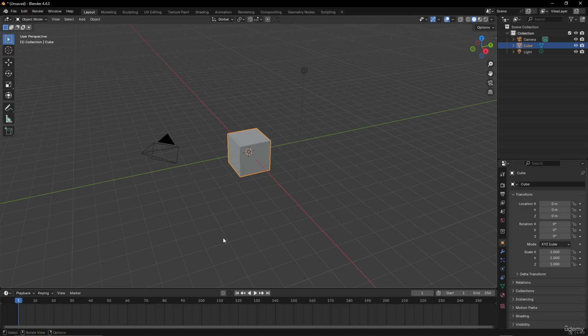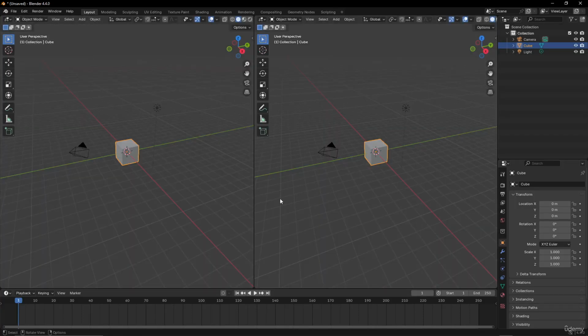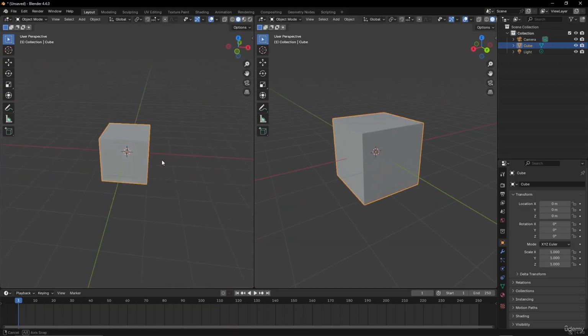For example, you can manage your own interface. If I have the double arrow like that, I can make a right click here and make a vertical split like that or like that. Okay, if I have this vertical split on a 3D view, I will have two 3D views now, and I can manage from a view here and from another view like that. So it can be useful to make some modeling, to have the right side, for example, and the front side. So very useful.